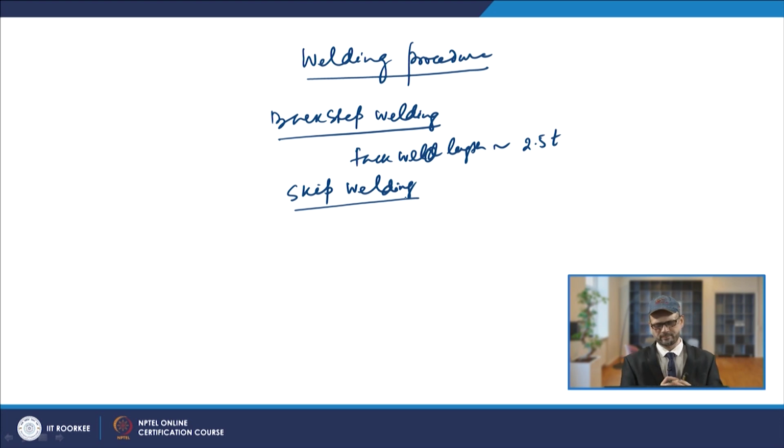This proves to be very effective in reducing the localization of residual stresses, and it is normally practiced in the welding of cast iron. These two methods are normally adopted for controlling residual stresses.